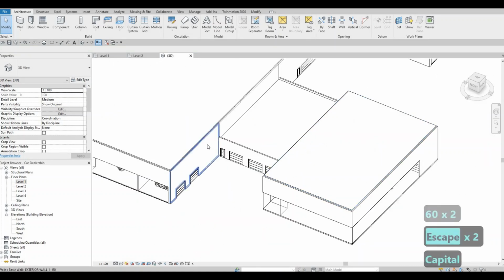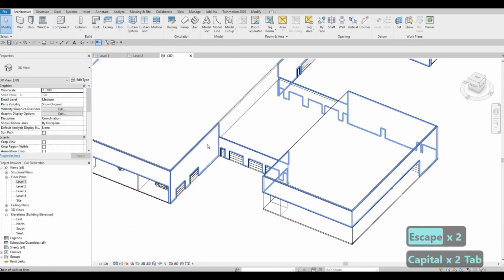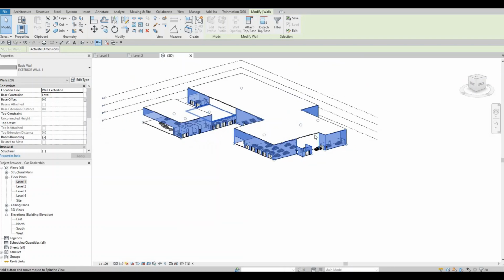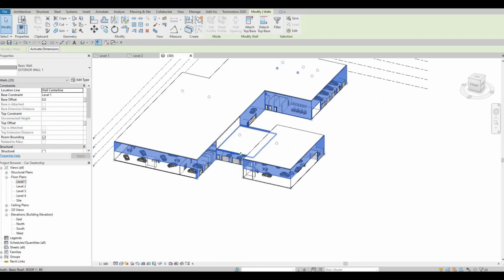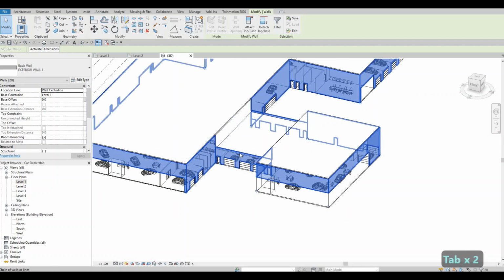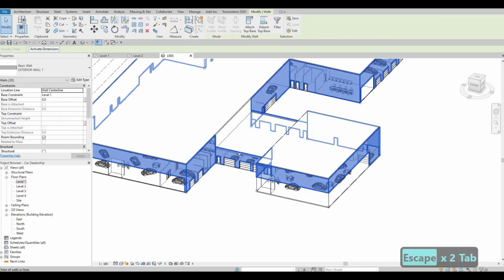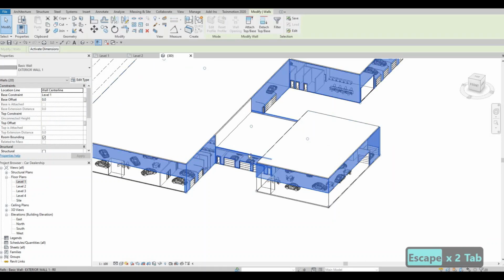and then here we need to select, so highlight everything. This will be just clicking on tab, and it will highlight every exterior wall that we have. And then let's just unhighlight this part. So hold on shift, so do it again, and then just select this one so that it's not included, and then the top offset is 600 again.